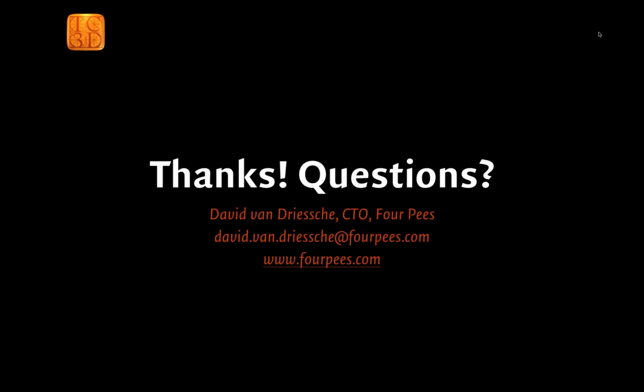If not, let me just summarize what we talked about here. The main part of this webinar was about the lighting environments, environment maps and lighting maps in iC3D Suite. And please remember the trick of pressing the S key on the keyboard and then using your mouse to rotate the lighting environment without rotating the object. That's perhaps the most important technique in there.